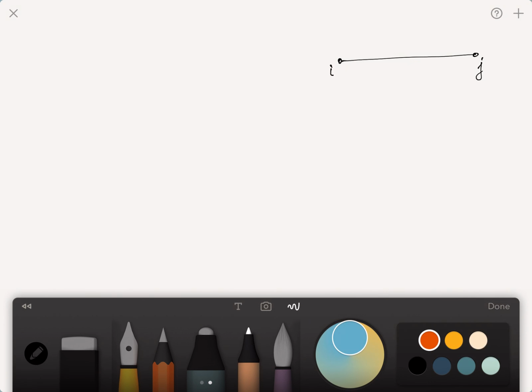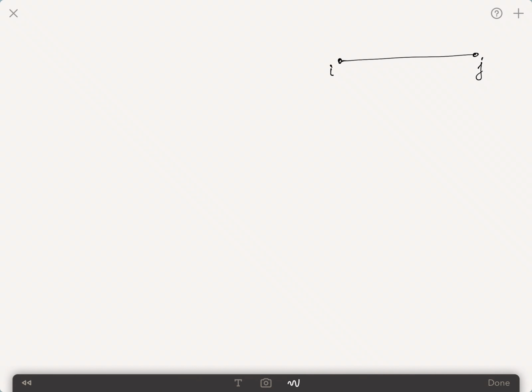So let's say we want to take this truss element. Very simple. I have 2 nodes i and j, and if I want to use a higher order interpolation function on this truss element, in order to be able to do that, I have to introduce an extra degree of freedom. If I want to introduce an extra degree of freedom in an axial element, then I have to introduce an extra node somewhere along the length of the element.